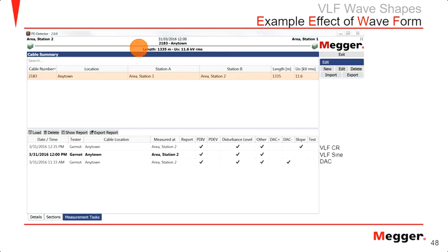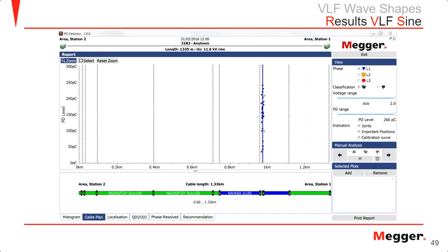Length is about 1.3 kilometers. And you have a couple of different kinds of cable attached to it. In this picture, you can see these different colors represent different types of cable. So one might be XLPE, the other one be EPR. So it's a mixed cable, and all these little rectangles represent a splice or a joint in that specific area.